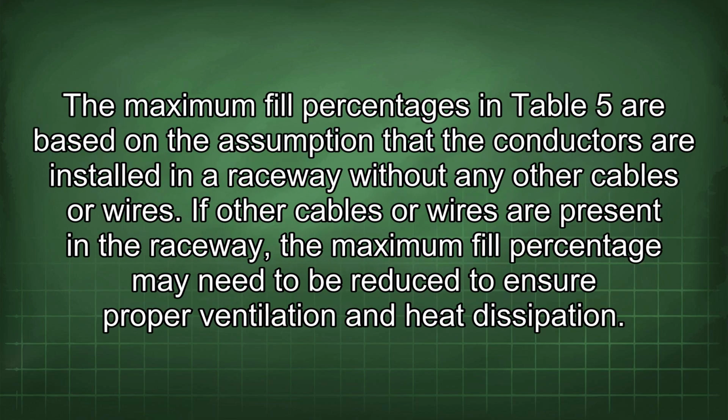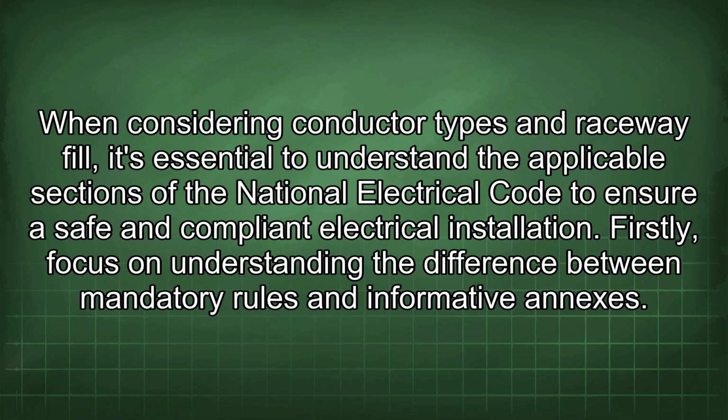The maximum fill percentages in Table 5 are based on the assumption that the conductors are installed in a raceway without any other cables or wires. If other cables or wires are present in the raceway, the maximum fill percentage may need to be reduced to ensure proper ventilation and heat dissipation. When considering conductor types and raceway fill, it's essential to understand the applicable sections of the National Electrical Code to ensure safe and compliant electrical installation.